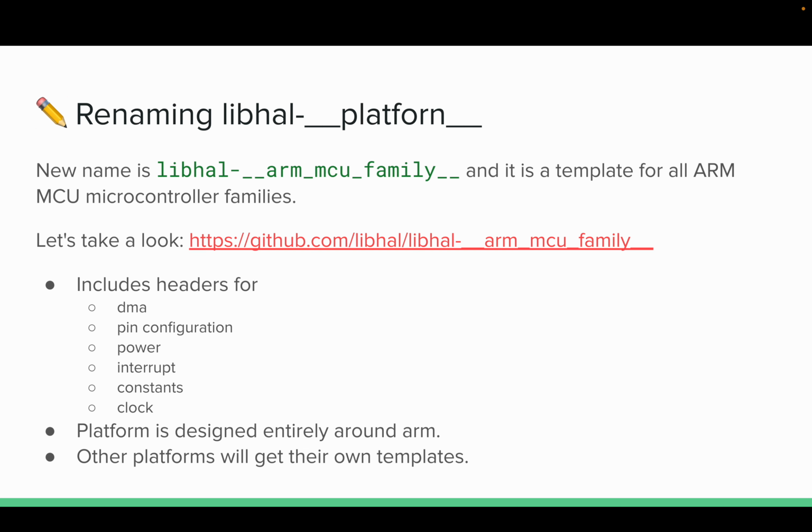And then maybe a few other things, like, are we using an external oscillator? This is a useful API, and the idea is that this would actually hit the real hardware to get this information. In general, you don't usually need to inspect this information. The code could, but I don't know if it's that useful. It's specifically useful for drivers that the datasheet tells you need to ensure that they're using an external oscillator, otherwise they are unstable. An example of this would be CAN for LPC40.